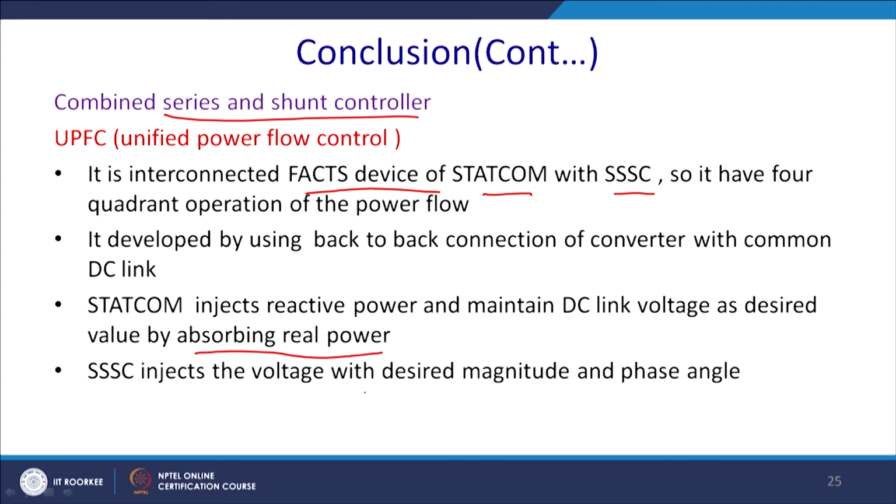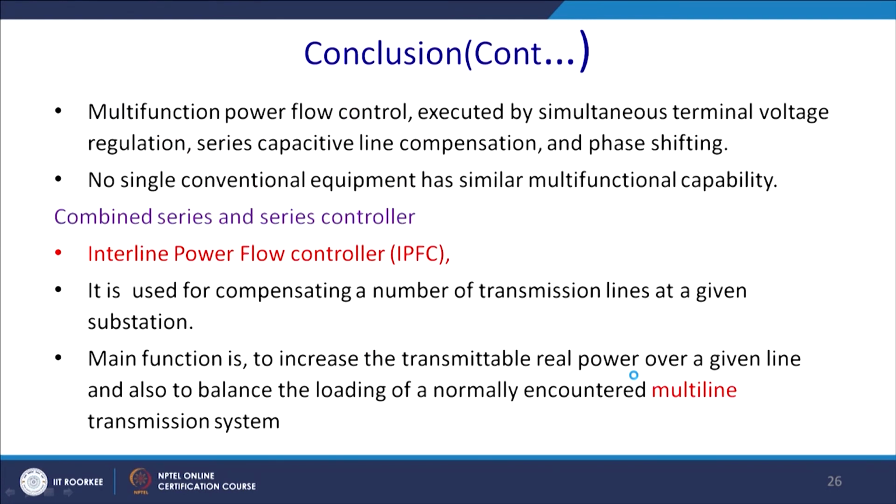SSSC injects voltage with the desired magnitude and phase angle, and multifunctional power flow control is executed by simultaneous terminal voltage regulation, series capacitive line compensation and phase shifting. All are possible, thus it is quite a versatile device. No single conventional equipment has similar multifunctional capability. So, thus UPFC is basically the solution.